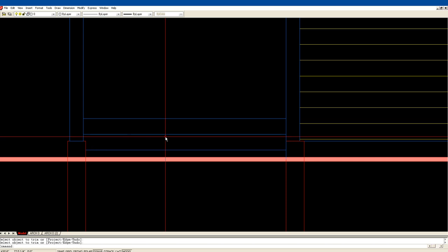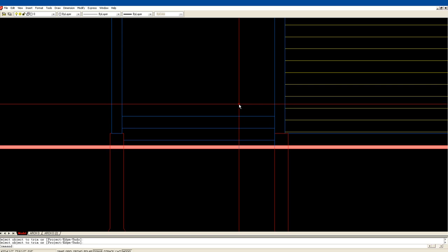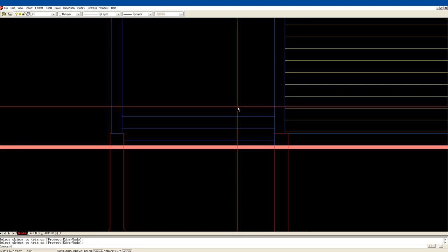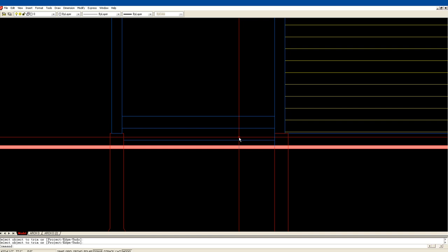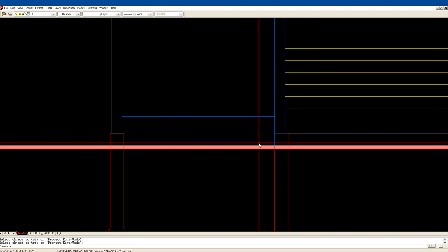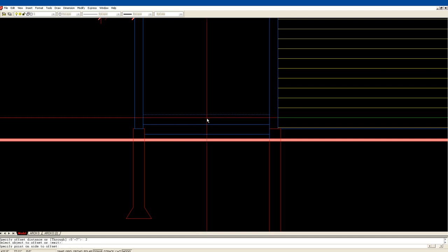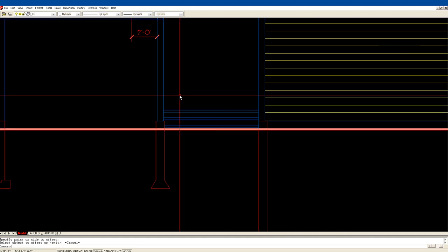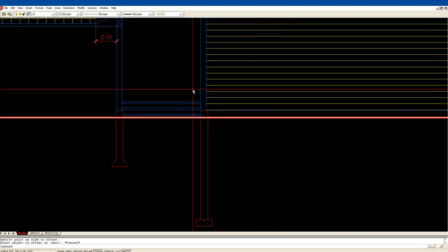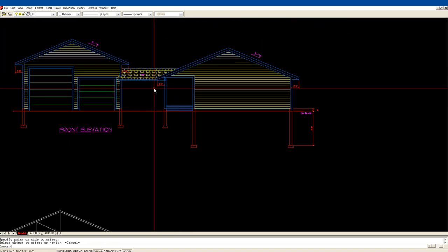And again, we're just showing the fact that he has to rise up a few stairs to get to this deck, to get to the floor height. And how he actually does it is really up to him. He may have more of a riser, or he may have less backfill. Backfill might be lower, and he'd need another step. Anyway, it's all done on site. I'm just going to offset 2 inches just to show the fact that there is a 2-inch piece of material to make that tread, whether it's a 2x10 or 2 2x6s, depending on how he builds the steps themselves. Okay, so that's pretty much it for here.